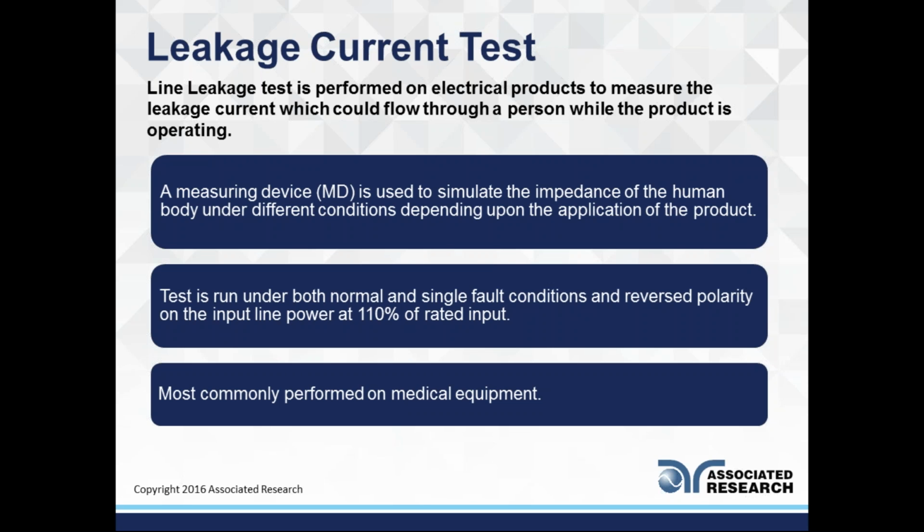This is why leakage current testing is huge in the medical field, because it's one of the few applications where electrical devices are literally attached to us. So any current flowing through it won't depend on whether I'm touching it, grabbing it, or walking by. It's connected to me. Stuff like watches, new electronic watches.